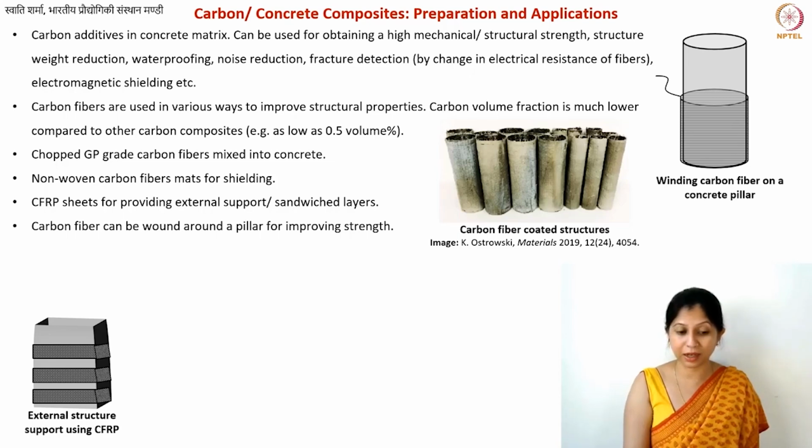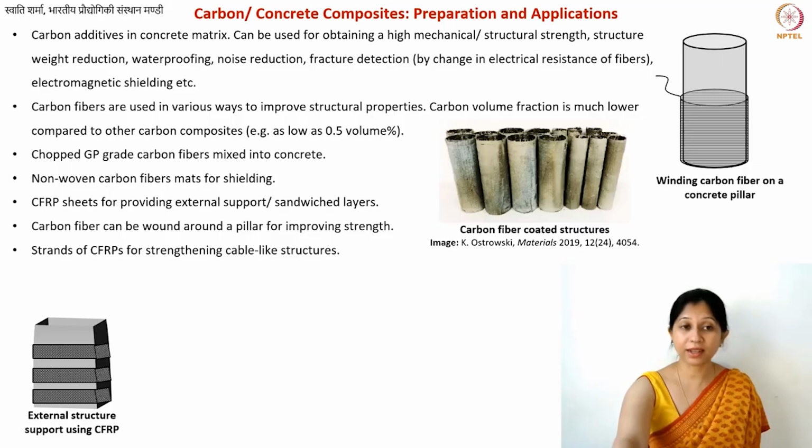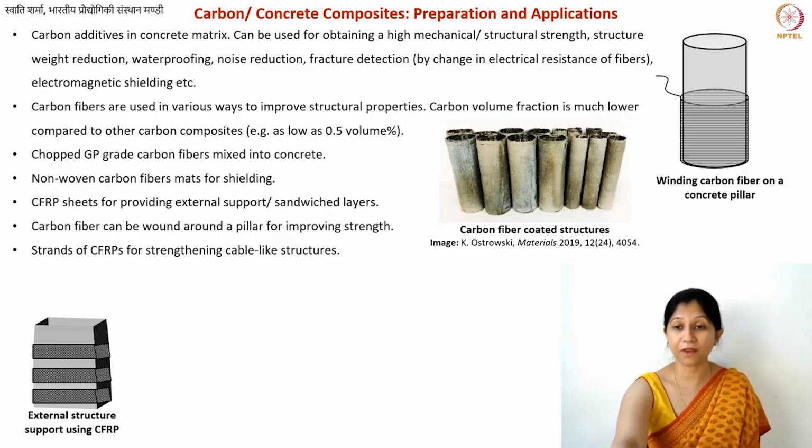derived carbon in this particular case, because you don't really want to go for mesophase pitch, because you don't much care for the modulus here. Tensile strength is more important, and turbostratic nature can also offer a little bit of strain hardening. So you may want to go for these kinds of fibers. Okay. Strands of these CFRPs, not necessarily fibers, but also with the resin.